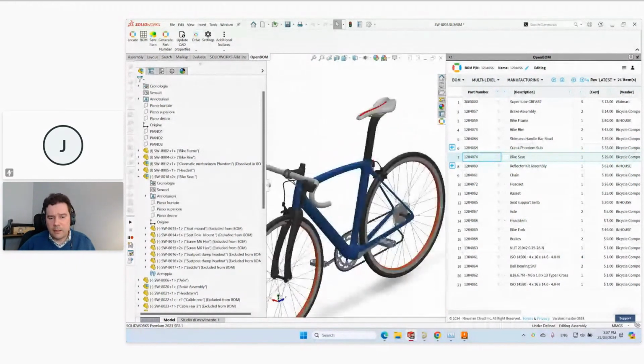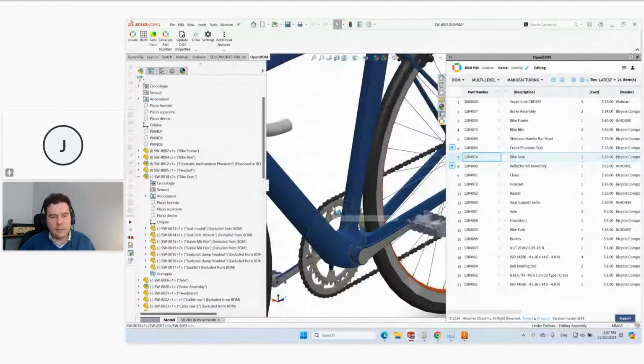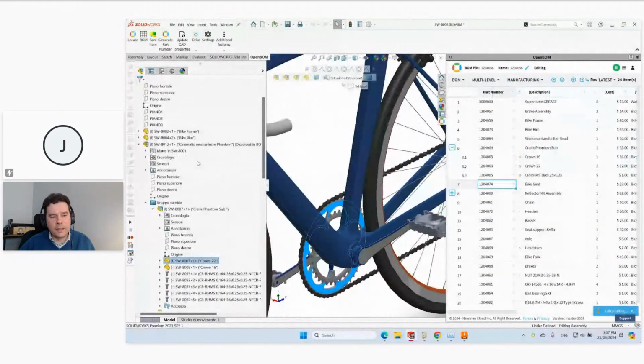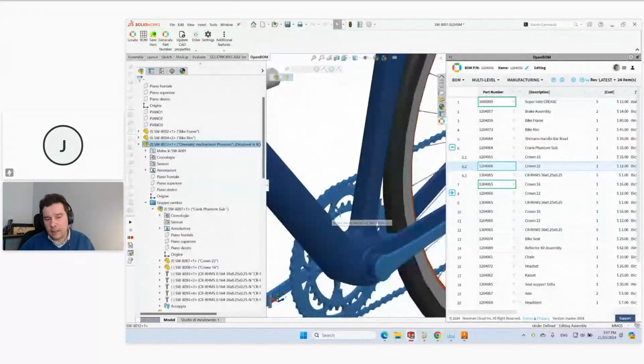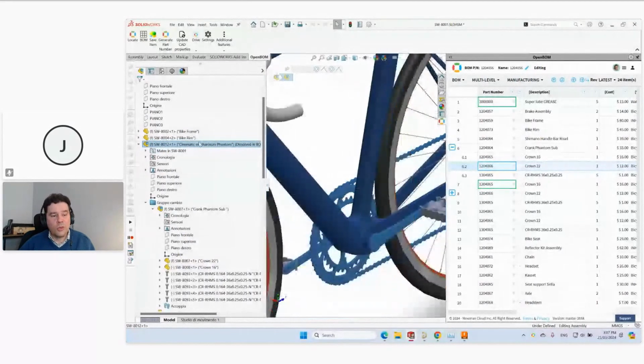So, for example, let's say you have an assembly that is for drawing purposes only. Like it's for performance of SolidWorks, or to show on a drawing. So you don't actually physically assemble a chain and this crank element. So you basically don't want to track this assembly. So you can filter it by saying you want to promote this, in this case in SolidWorks.